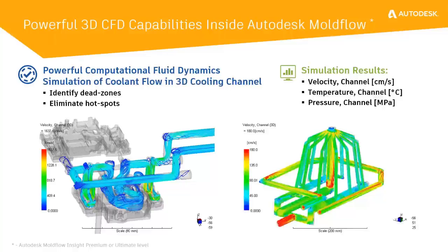As I mentioned before, Moldflow has a specific way to solve the coolant flow and heat transfer calculations by leveraging the Autodesk CFD meshing and software. It's important to understand that coolant flow through non-traditional channels is a complex problem, which really requires a more sophisticated calculation method than the traditional pipe flow calculations. This is why Moldflow leverages the proven Autodesk CFD meshing and solving technology directly inside the Moldflow interface. This is critical to ensure the intended design can deliver the expected results.